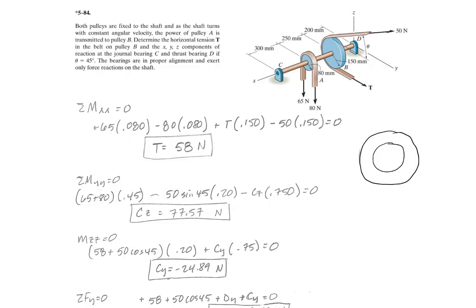In this case, we have some bearings supporting the shaft, and we want to make sure that the forces on them don't exceed their limits. We also have an unknown force here. We have a 50 Newton force on this side of that pulley and an unknown force here. So a moment about an axis approach is the best way of looking at this. Again, it's a scalar approach. That's what we were doing in the prior look as well.